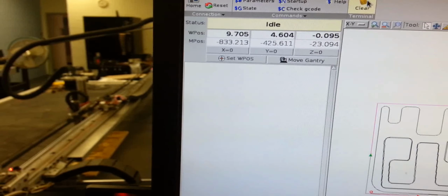So if we go over to the actual code for this, you can see scoreboard wire traces.txt. This actually starts at line number 30, G20, G94, G90, G90.1, and you just don't see that behind here. So we can go down to 205, and it looks like it started with that one for no apparent reason.